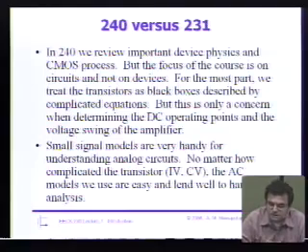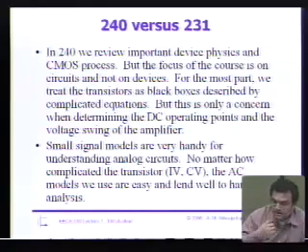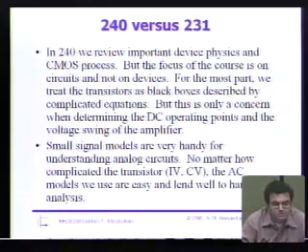In some ways it's funny. The only place that really concerns us is when we're doing the DC operating point of a transistor. That's where we need the full-blown IV-CV equations, mostly IV equations for the DC operating point. And really, when we're doing design, we need small signal models. So what we'll find in this course is we're going to use the simulator to tell us the small signal parameters. We're not going to try to calculate those from a simple square law model, which is going to be grossly inaccurate. But once we do that, we can do hand analysis.